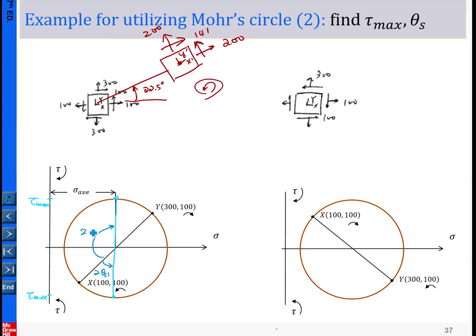If you choose 2 theta s2, such that this is our y point, the x point will move to here. This is our x prime, and this orientation follows the same sense. So y will move to y prime here. So x prime equals 200 and 141, and the sense is this. Y is 200, 141. The sense is this. Again, the y prime is located on the lower quadrant, so we take this sense, and in this upper quadrant we take this sense. Okay.